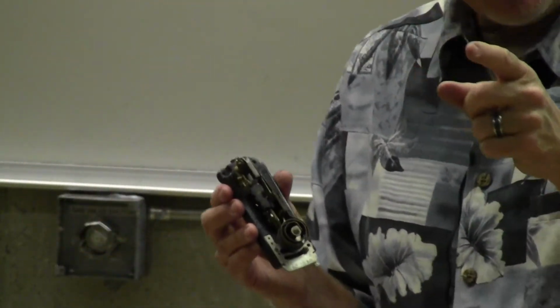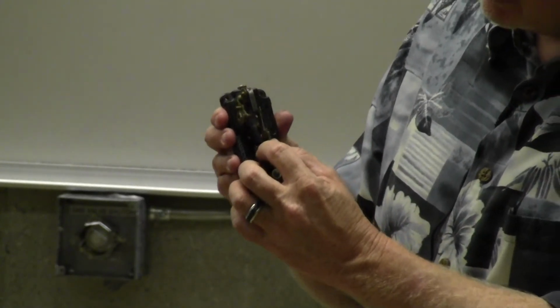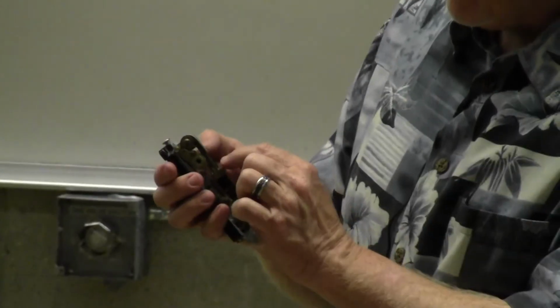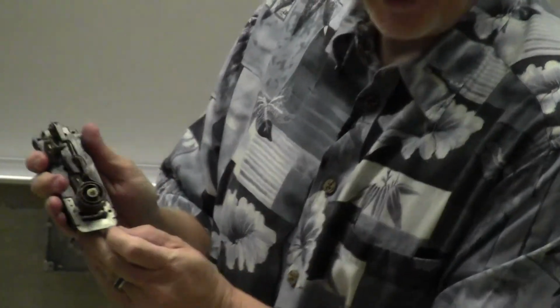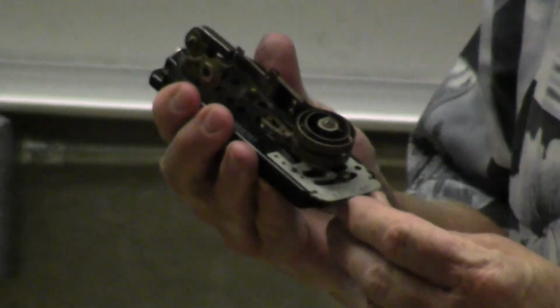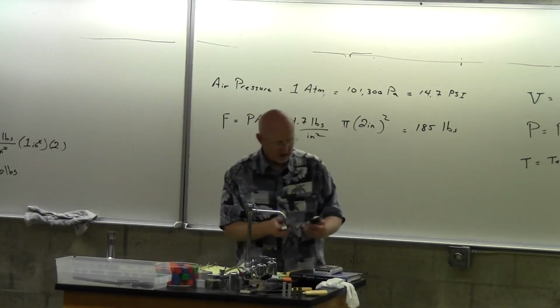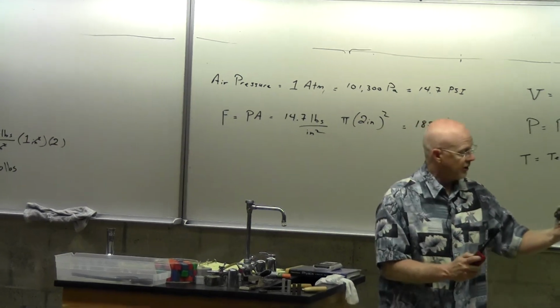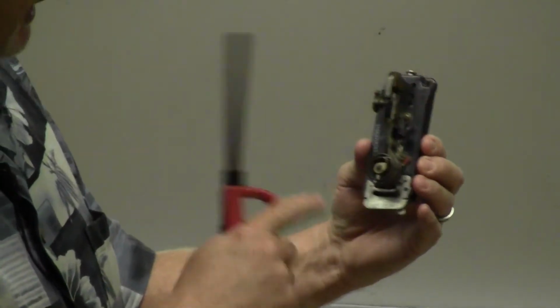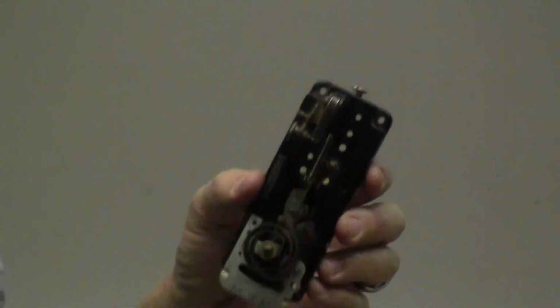But if it gets cold in the house or the apartment, this then will contract. And eventually when it contracts enough, depending on how you adjusted it down here, it'll make electrical contact. So you, the operator, decide when you're going to make electrical contact and when the furnace will go on. And so like this one, I set right here, it makes contact at 80 degrees, and then anything lower than 80 degrees, it goes on. And so actually maybe this would be enough to actually see it alone here, is right now I have this coil making contact. And so you might say, okay, right now it's cold in the room.